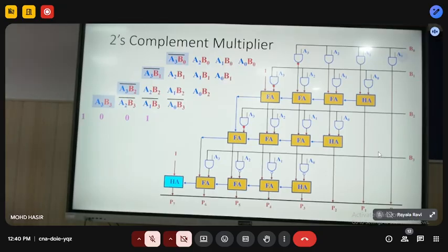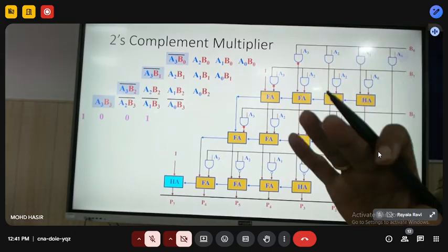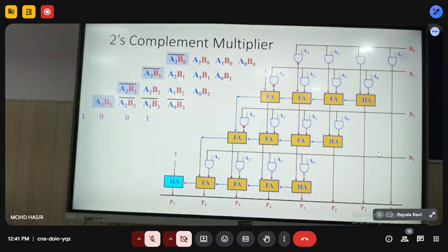By that you can understand what are the operations required, which part is sequential, which part is combinational, what is the boundary condition which I need to take care of. If you put numbers all one here, then it is a boundary condition. Intermediate will work if it is working for boundary. Otherwise, sometimes you will come up with hardware which may not be optimal. So don't start your work blindly. If you have an algorithm, try to implement it in a higher level language. Understand which part you can partition into what side.